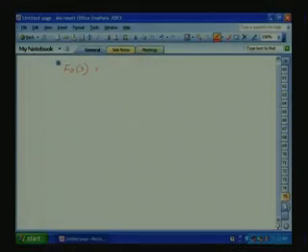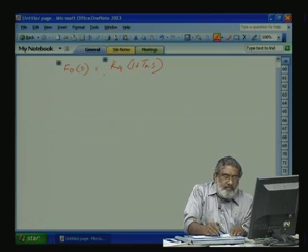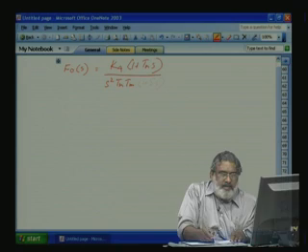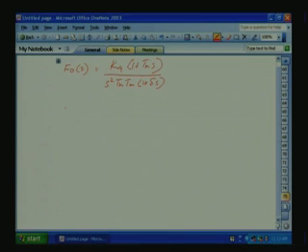Last class we were trying to design the speed loop using symmetric optimization with the graphical technique. There we considered the loop gain. So, finally, we got the open loop gain transfer function: K4 into (1 plus Tn S) by Tn Tm S square into (1 plus delta S).